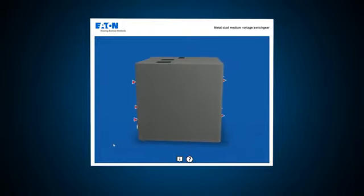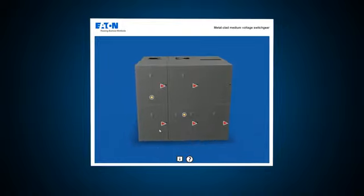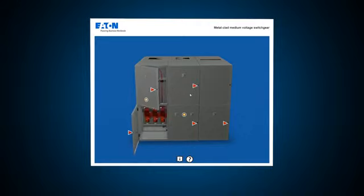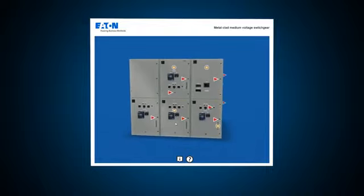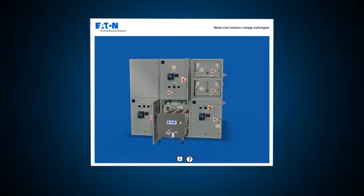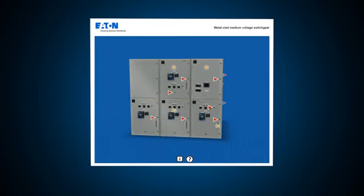Air insulated switchgear, AIS, is defined by the IEEE C37.20.2 standard for metal clad switchgear, and the IEEE C37.20.3 standard for metal enclosed switchgear. In metal clad switchgear, all electrical components, including the incoming bus, the outgoing bus, instrumentation, and main circuit breaker or switch, are enclosed in separate metal compartments to provide an additional level of safety and ruggedness. Metal-clad switchgear features draw-out circuit breakers for ease of maintenance and is often applied in industrial facilities and in electrical power generation and power transmission facilities.